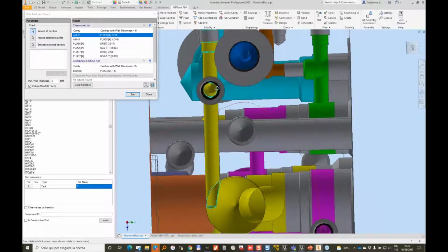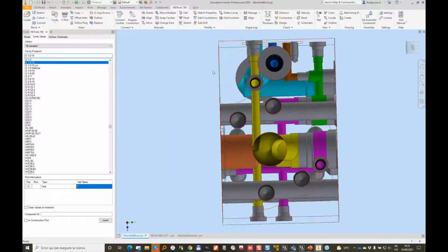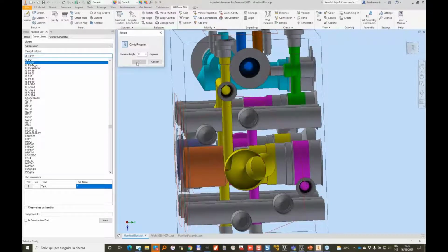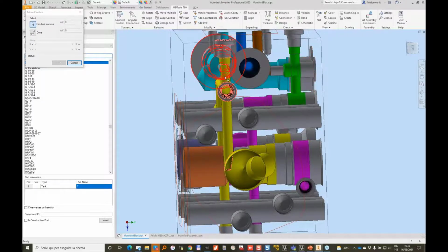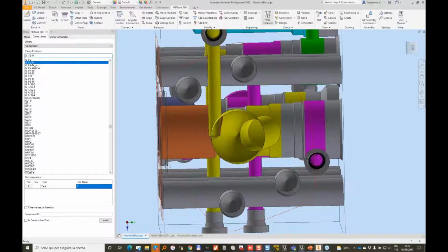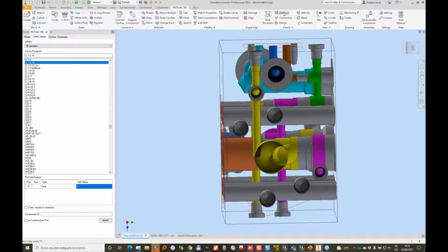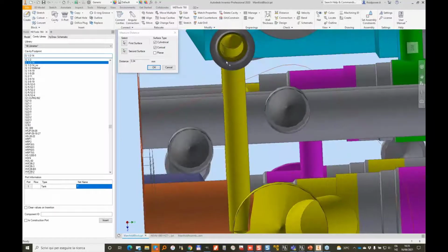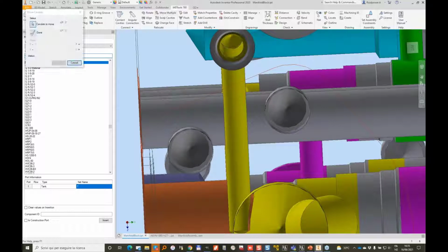So let's move everything slightly. I really don't like this design made this way. Well, in any case, let's move 1, 2, and 3 by 1mm. So now we can just do a wall thickness. Well, let's measure the distance. Distance between this and this is, second surface is this one, 4.78. It's okay. And we take this one. It's 3.34. So let's stay 0.5mm to the right. Move multiple.